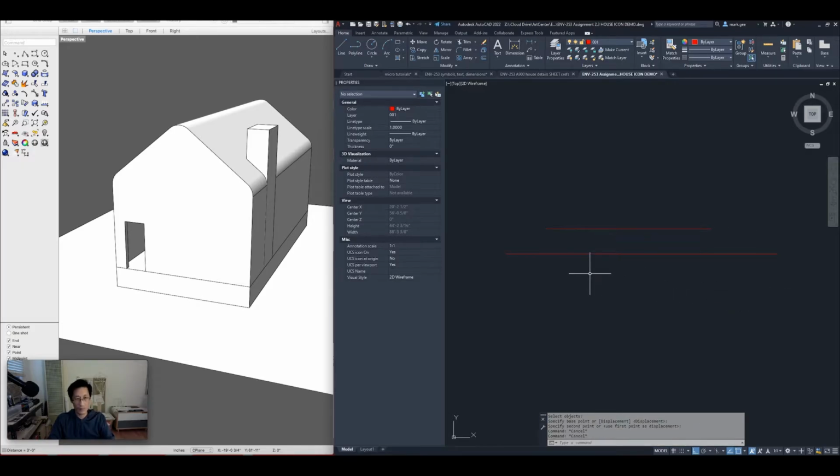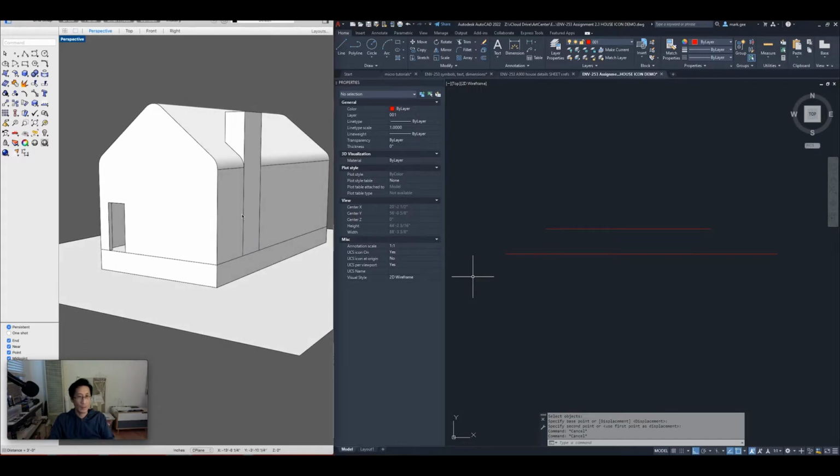Then I'm going to check the Rhino model again, and what I want to do here is find out where this breakpoint for this curve occurs. And I'll do a distance, and above our floor level there, that's 12 feet, 2 1/4 inches.